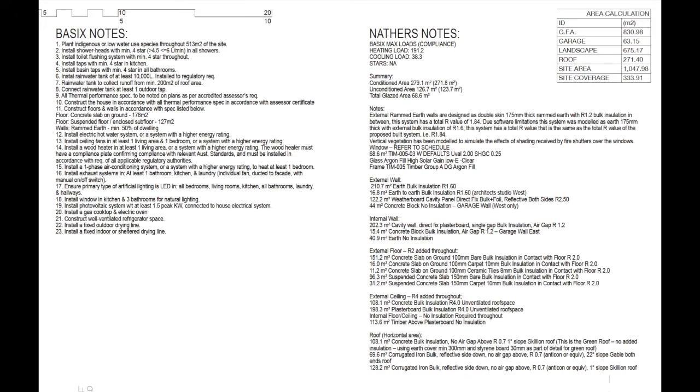If it's a complicated project, then beyond the BASIX requirements, we also may have NatHERS requirements. NatHERS stands for National Housing Energy Rating Scheme. And again, if it's a big building or a complicated building, we may not be able to get the BASIX approved as a DIY method. So it may need to be more a performance assessment. That assessment might be done in a few different ways, and that's going to show more detail about the way that the heating and cooling loads are calculated. So again, that information may need to be communicated on the site plan.